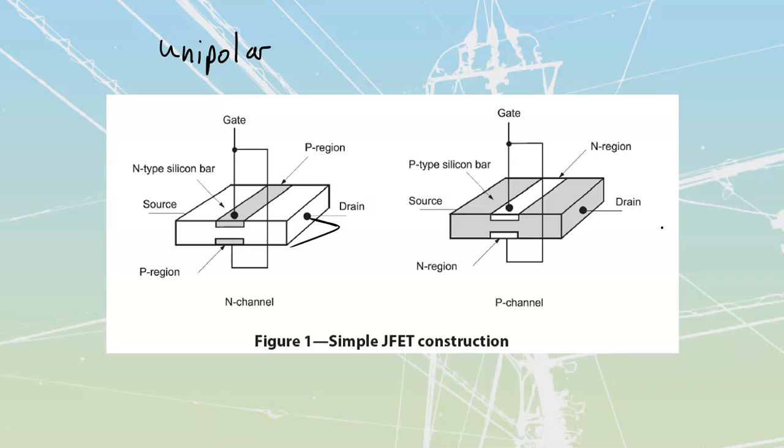And the FETs are used as well because they have this beautiful thing where my gate current, my control current, sees an impedance that is really, really high. The way the book talks about it over here says that they've got a high input impedance. We're not talking about the impedance across the main run. We're talking about the gate impedance. The gate impedance is going to be very, very high, which means that the amount of gate current, there's always going to be a tiny little bit of leakage gate current, my IG, is going to be very, very, very small off of these things.